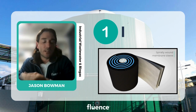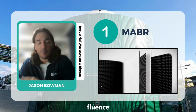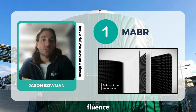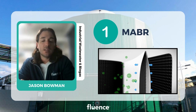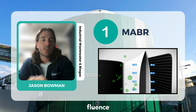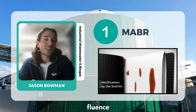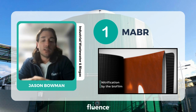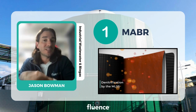Digestate tech number one, MABR. So let's talk about MABR first. So MABR is a relatively new name in the industry, but it has been around and proven for well over a decade. So the easiest way to think about this is picture a closed membrane where we inject oxygen to the inside of the membrane. So only oxygen is allowed to diffuse through the membrane from inside out.